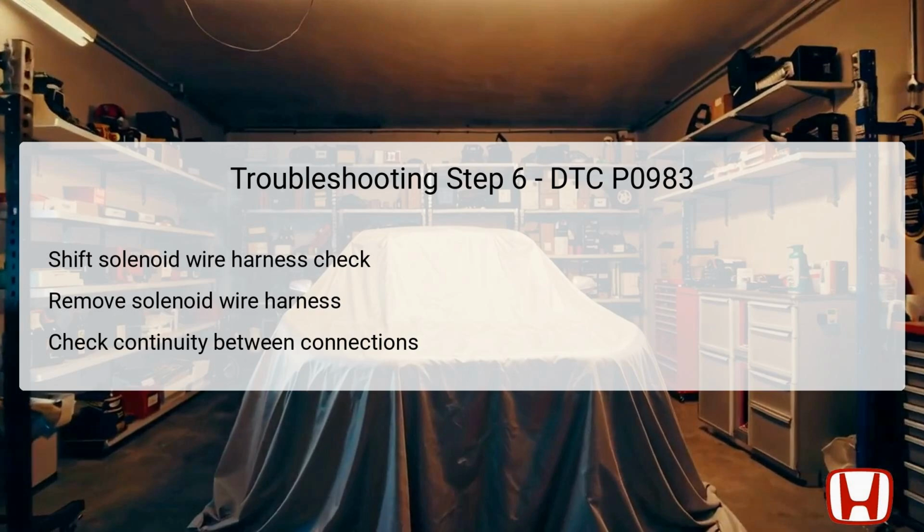This involves comparing connections from the yellow wire at the solenoid valve D1P connector number 1 to the yellow wire at the shift solenoid wire harness 7P connector number 4. A successful continuity test confirms that the wire harness is operational. If the test reveals a lack of continuity, this indicates a fault in the wire harness itself, necessitating its replacement